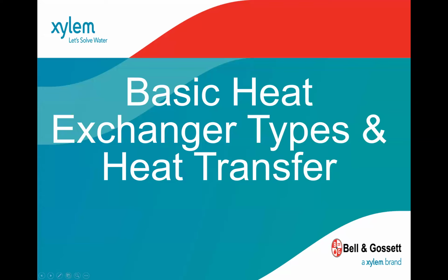On the far left-hand side, sorry, here's my phone here. On the far left-hand side, you've got what we call our BPHE. It's a brazed plate heat exchanger. So that's one where the plates are brazed together. You don't have a gasket. The unit on the far right, that's a plate and frame. It also has plates, but this one's in a frame, so it has gaskets in between. You can remove it and service the heat exchanger.